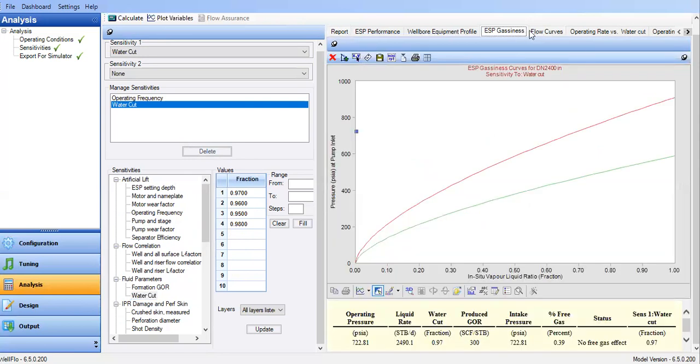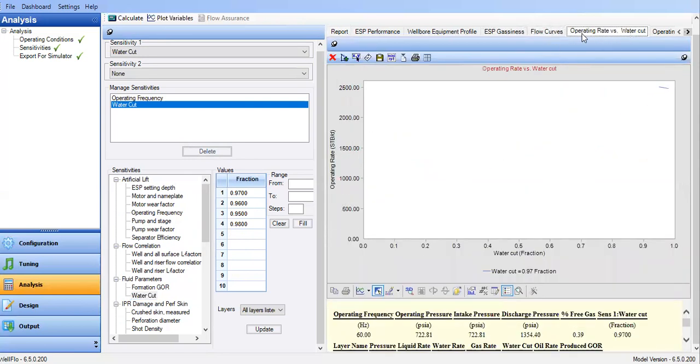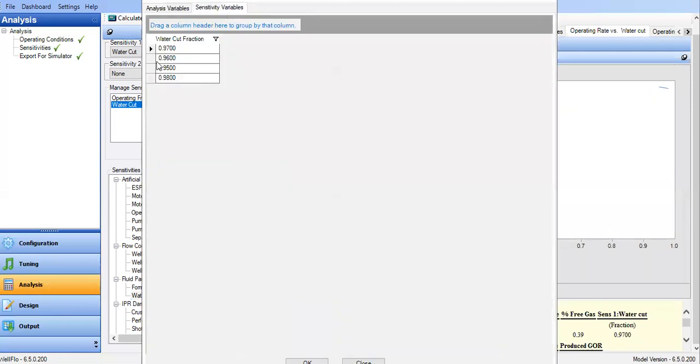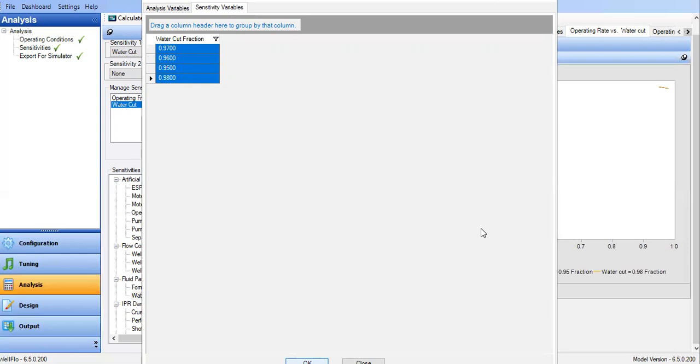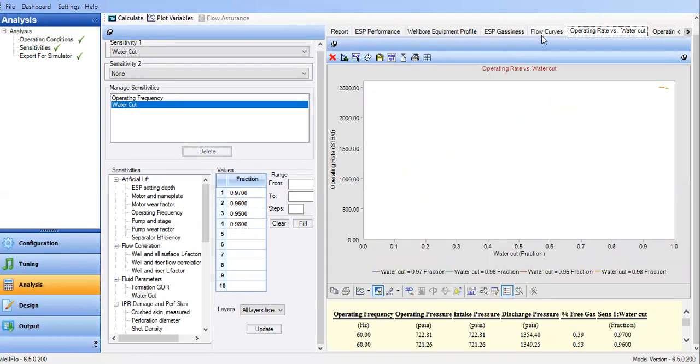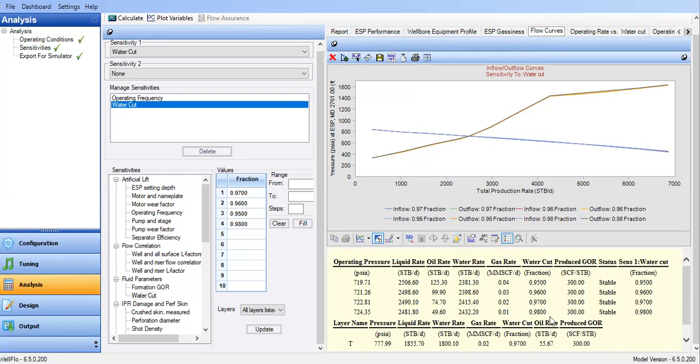If after commingling the production I get the water cut of 98% as opposed to 98.5%, I can get the flow rate of 49, which is even greater than the previous oil gain of 37 barrels of oil per day. Okay, so you see the point.